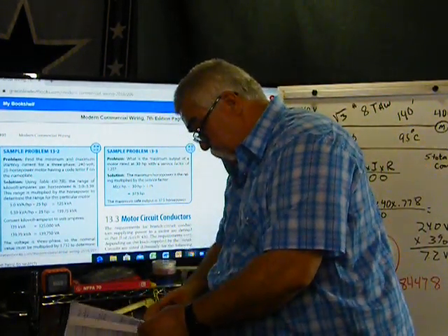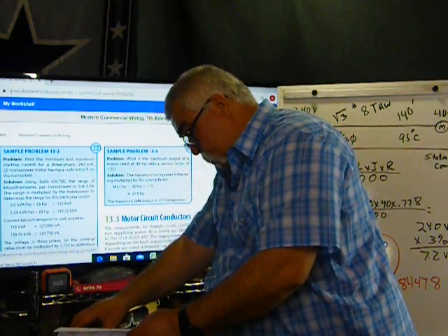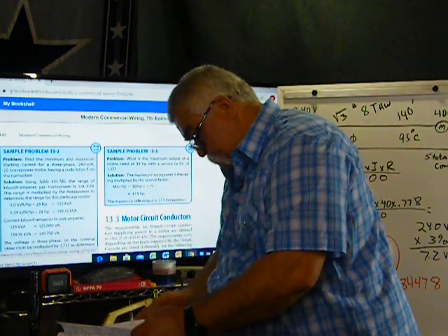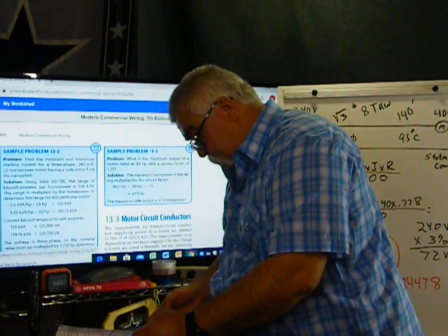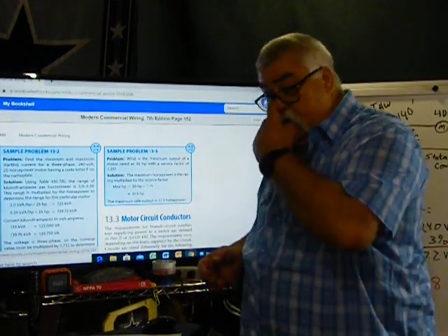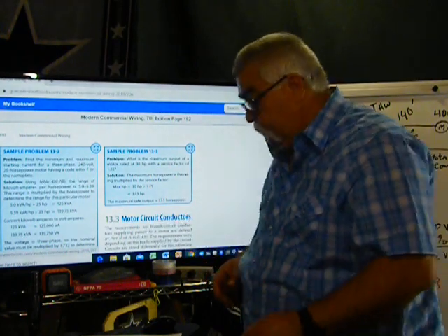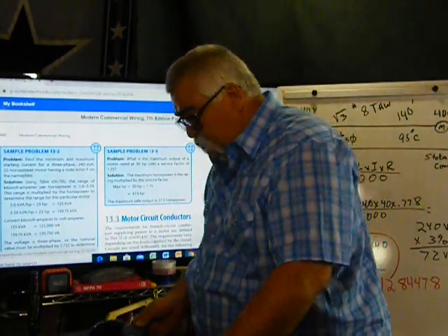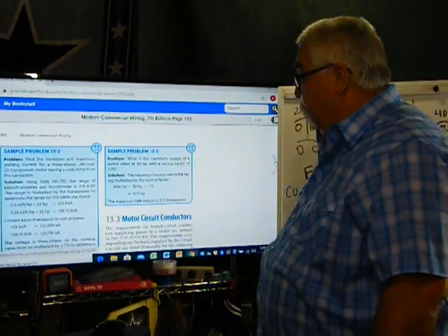Voltage drop, wire sizing, conduit sizing, box sizing. And remember, 6 inches. You have a conduit. You have wires going into a box. How much wire you're supposed to have? Minimal 6 inches, free clearance. I'll talk about the services. This is the majority of the stuff that's on this. I think I eliminated some of the other stuff because there was too much problems.